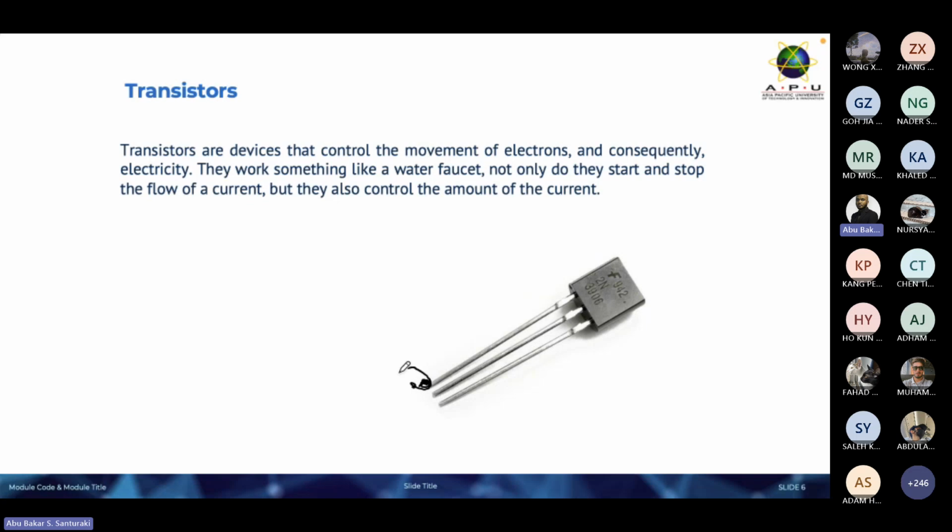This first pin is the in pin. This is the out pin. So electricity comes in through this first pin and leaves through the other pin on the condition that the gate is closed or open. So this third pin in the middle, if I send it a 0 signal, I'm telling it to close the gate. So whatever electric signal is connected to the in pin will not flow out. And if I turn it on, it will send a signal to open the gate so that the electric current can flow, whatever the signal in here is. So basically, this is the switch.